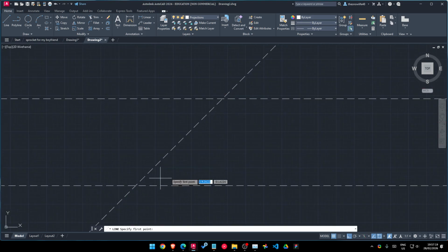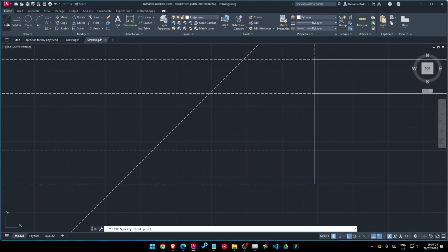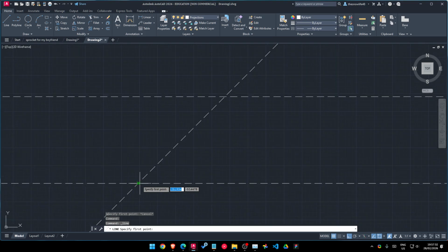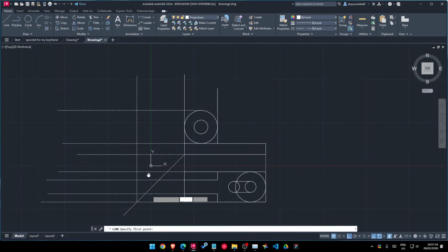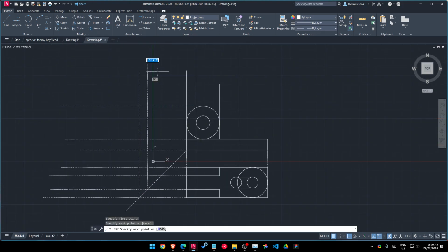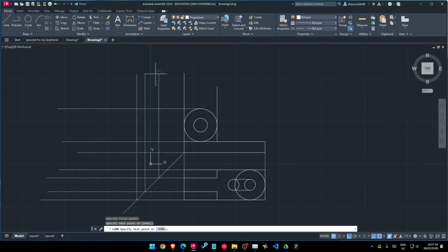Now these intersections are important. Select the line tool and draw perpendiculars, lines perpendicular to this horizontal line starting from this intersection. Wait for the cross to appear so you know it's snapped well, and just draw arbitrarily long lines. Doesn't need to be something specific because it's projection lines. Projection lines are meant to help us understand where we're supposed to draw.